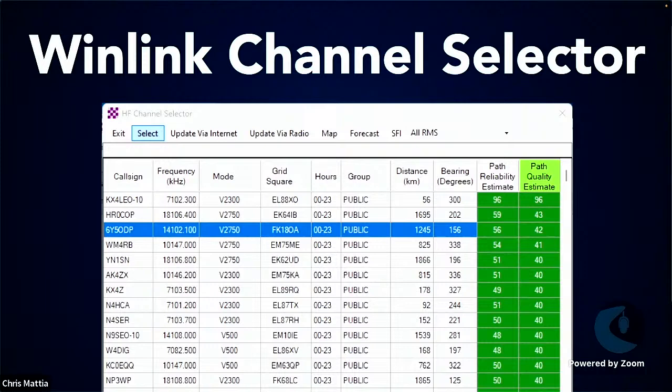So the first thing you want to do is look down that frequency column, and find the HF station or the HF gateway that is on the band that you are tuned to, that you're ready to set up and operate on, that's got the best likelihood of a good quality path to where you are physically located. You can just hop in there and make sure that you've got that one selected.